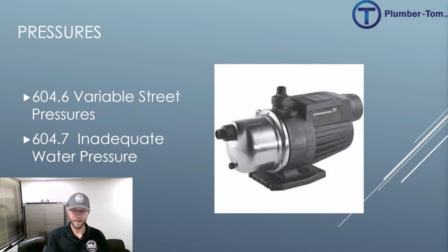604.6 talks about variable street pressures. It says where street water main pressures fluctuate, and they can go up and down, the building water distribution system shall be designed for the minimum pressure available. So if you know you're going to have high pressures and lower pressures, but it's all within this safe range, well then let's design it for the low end, just in case we end up there a bit, so that our fixtures will still function.